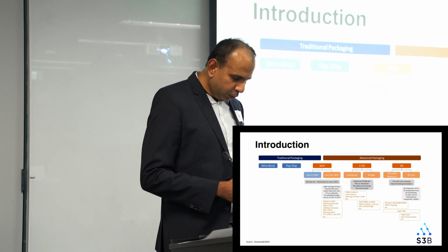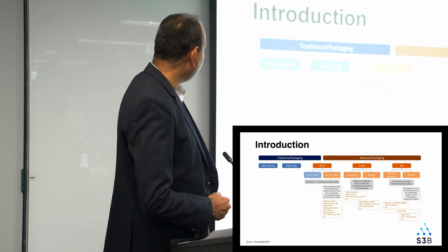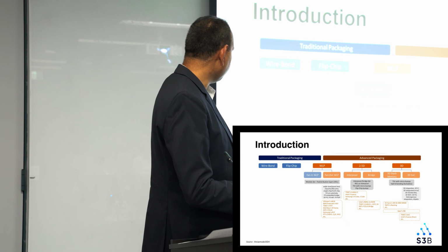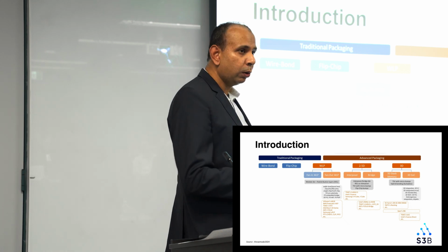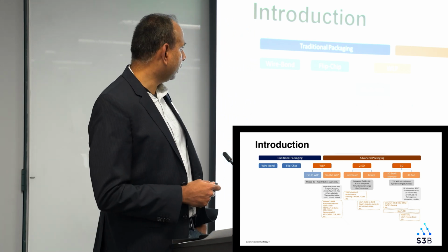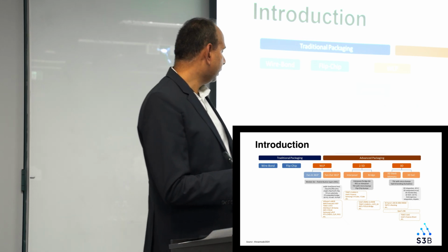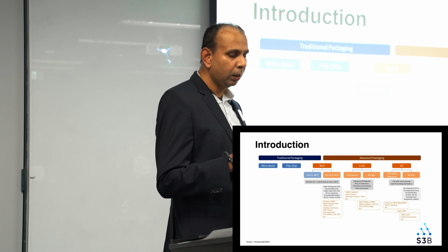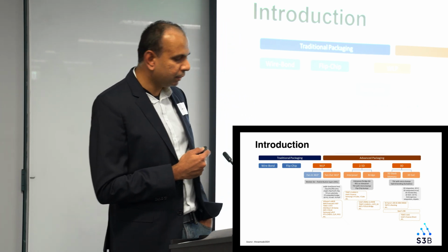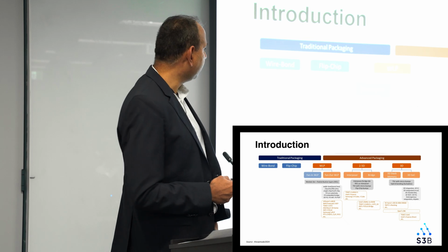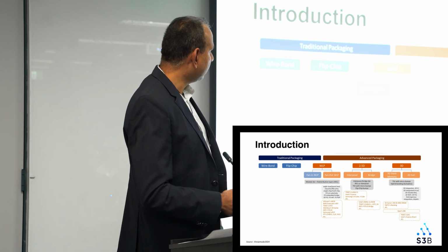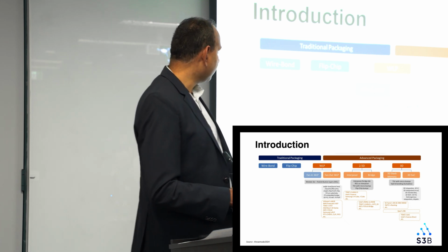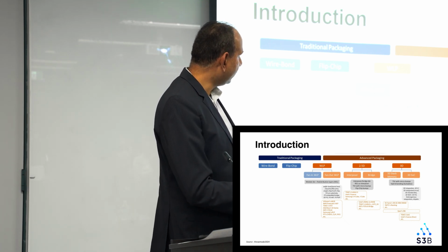If you look at the packaging landscape, previously with traditional packaging, we were mainly focusing on wire bond and flip chip. But advanced packaging started to evolve when the cost of economic scalability of silicon diminished, so people started looking into various packaging capabilities to have high integration density and reduce the interconnection distances between the chips. That's where a lot of foundries started looking into advanced packaging, which can be broadly classified into wafer level packaging, 2.5D and 3D.